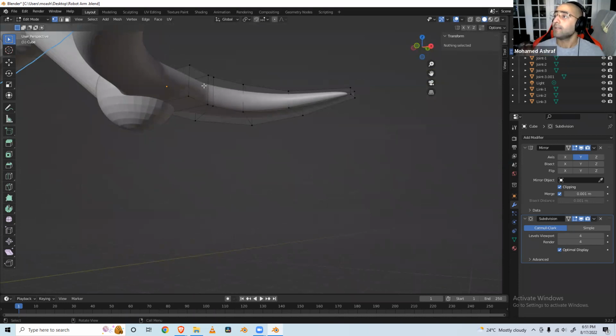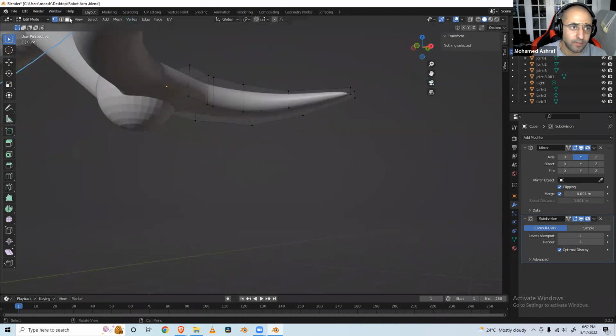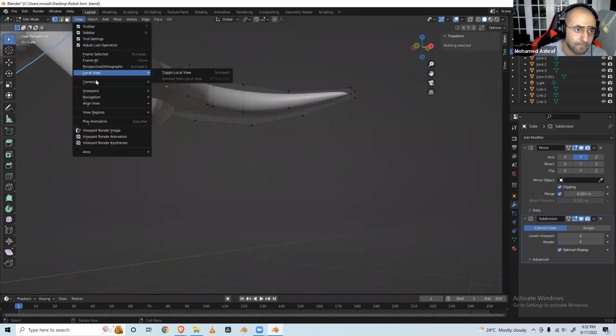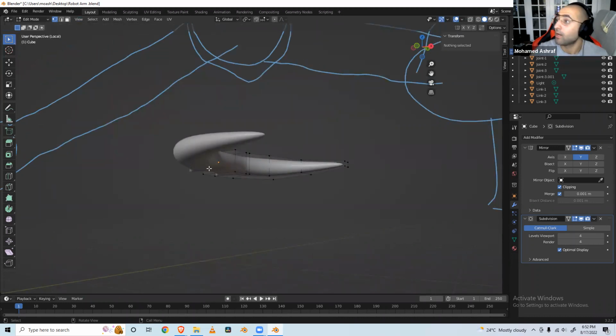You know something? A way to actually hone in and magnify and just isolate the object is by pressing the slash key. And slash is a really great way to isolate this specific thing, and it's on every keyboard, not just the ones with the numpad. I think another one you can do is, yeah, local view. Apparently it's called local view.